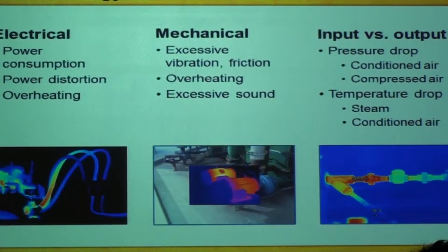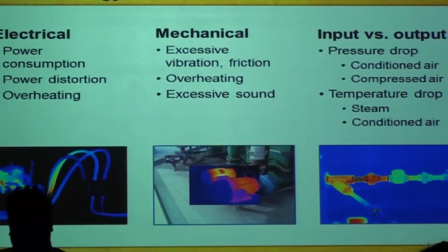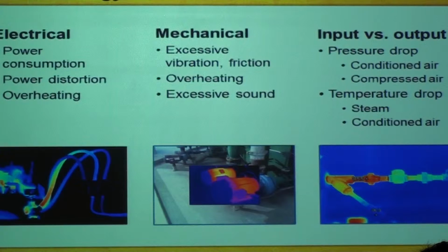Problems like the loose connection. If I have a loose connection, what happens to that loose connection? What's changing? If you look at the formula for power, I squared R, right? Cable losses, I squared R. What's changing when you have a loose connection between 2 contacts?